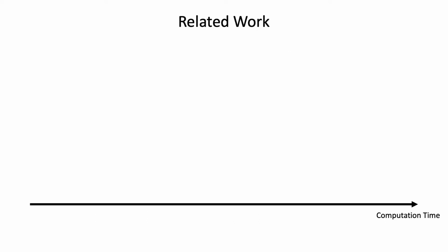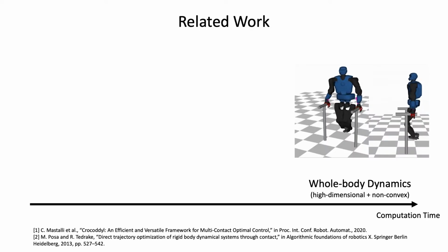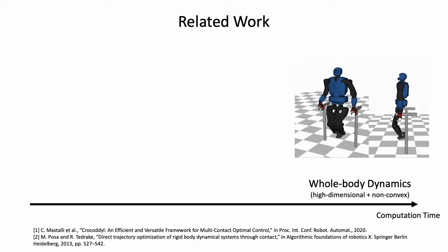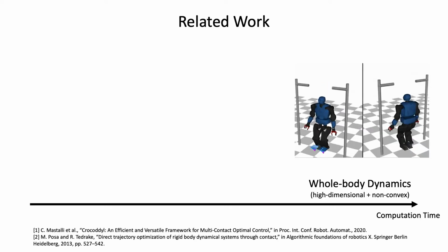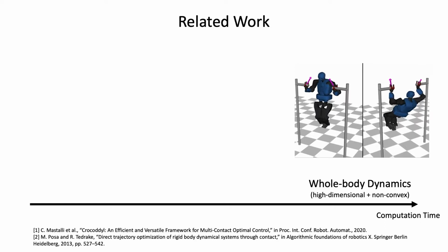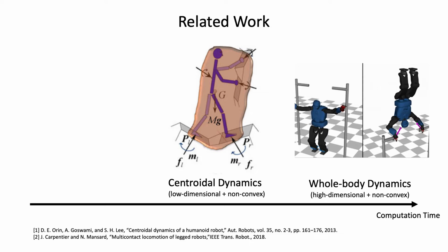Indeed, when synthesizing multi-contact motions, the complexity of the dynamics model has a large impact on the computation time. For instance, although impressive multi-contact motions can be generated by using the whole-body dynamics model, the computation time is usually far from the requirement for online usage, unless contact timings and locations are fixed. This is because the whole-body model considers the mass and inertia of every link, which results in high dimensionality and nonlinearity. Recently, the centroidal model has become popular for multi-contact motion planning.